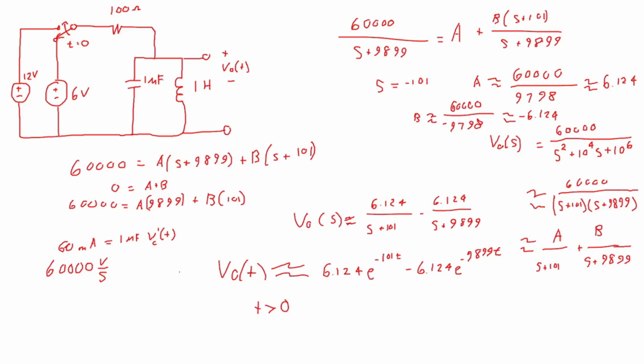And so there's massive resonance in here, and you get two very long-lived terms in your complex conjugate roots. So if you're overdamped, you get two real roots. One's really small, one's really big. When you're underdamped, you get two really slow complex conjugate roots. And when you're critically damped, that's when everything's all zippy and moving quickly. And so that's where those terms come from, the critically versus over versus under.